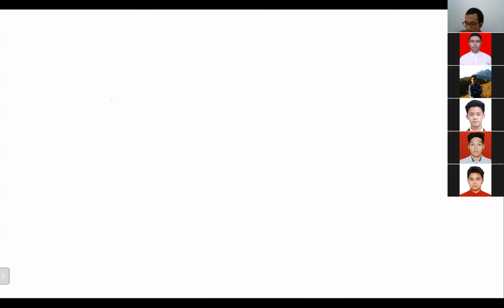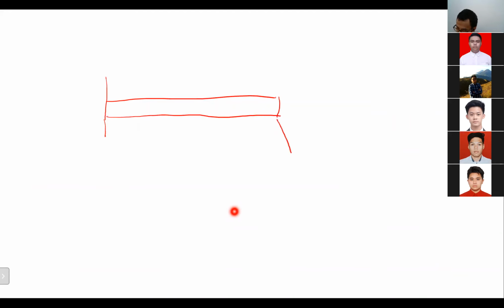So remember, we have this cantilever. At the beginning, the force is like this, F. Then we have to move this force to this particular point, right? Replace this with another force, F, where F is 8 kilonewton, plus a moment.